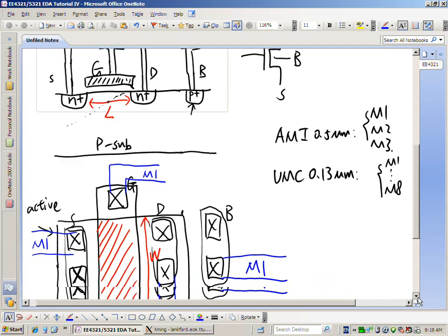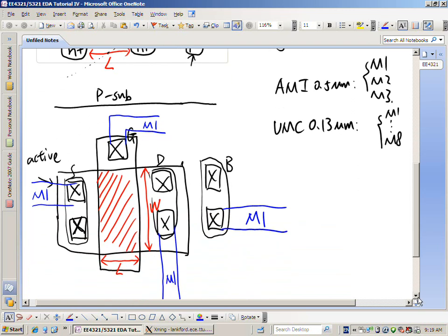And this is very important for next semester, the microwave solid-state circuit. In that course, we will learn the effect of the number of contacts on the gate. Actually, that will affect your noise performance, your gain performance a lot. When the signal frequency goes high, you have to minimize the resistance everywhere. Okay? Any other question?